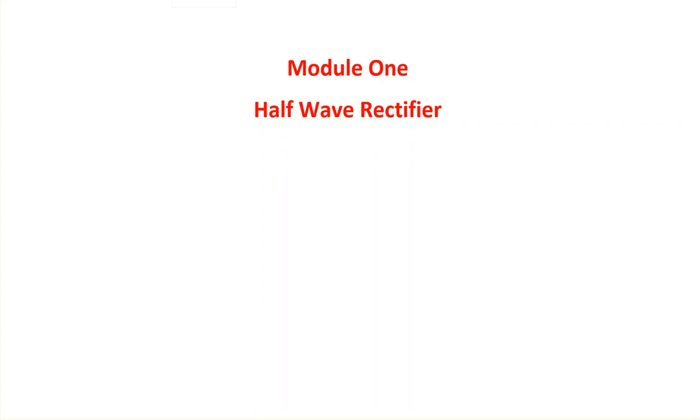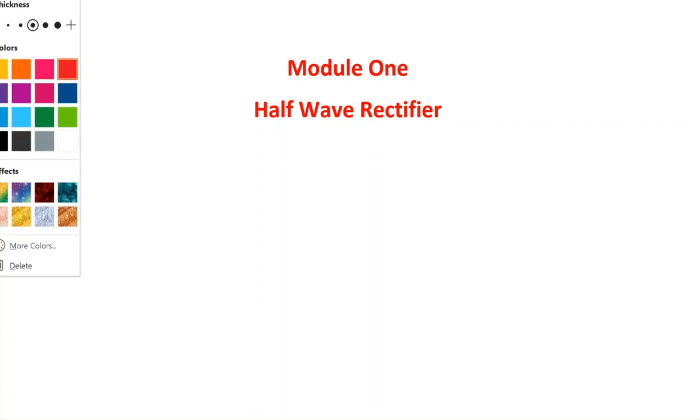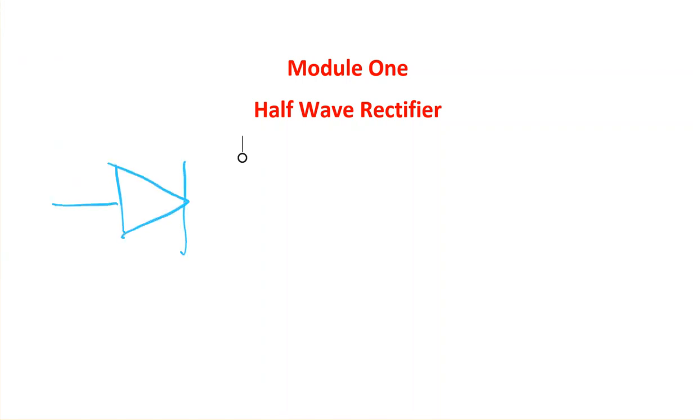So you remember very well that when we talk about a circuit where you have a diode, this diode will allow the current to flow only in this direction as long as the voltage, which we call VP, is greater than a certain threshold voltage. And as I just mentioned, this property will help us in making what we call rectification, or AC to DC conversion.